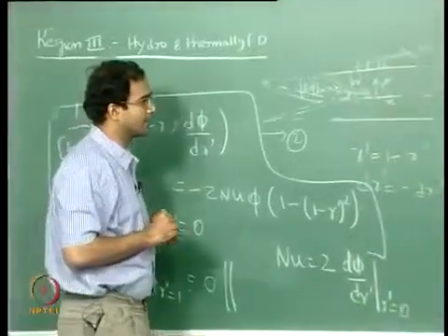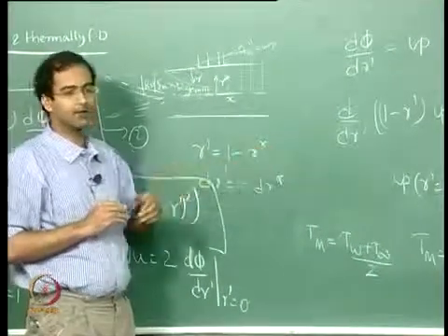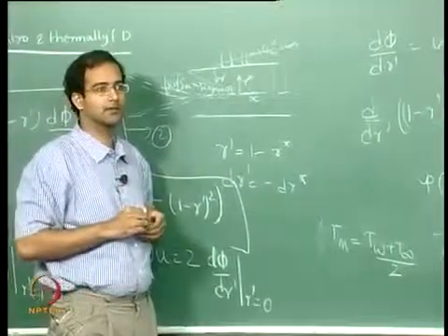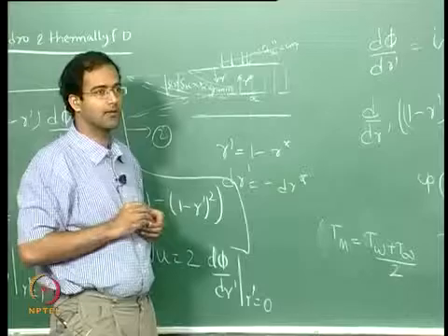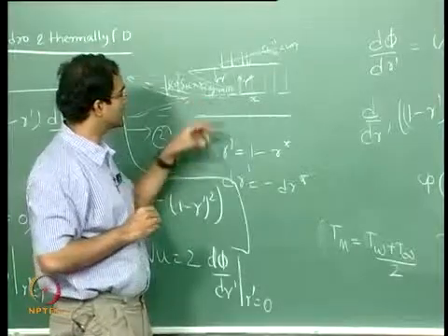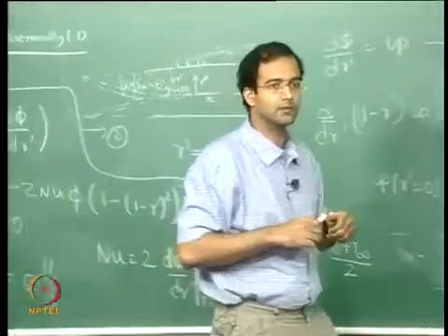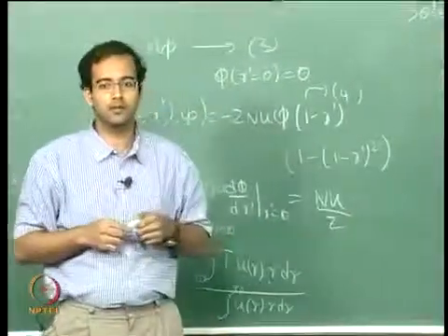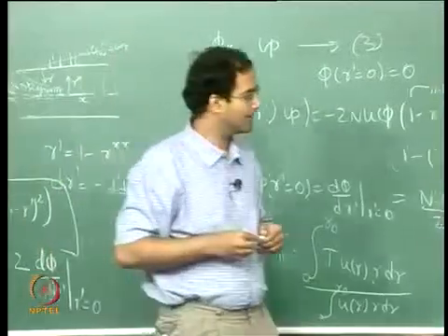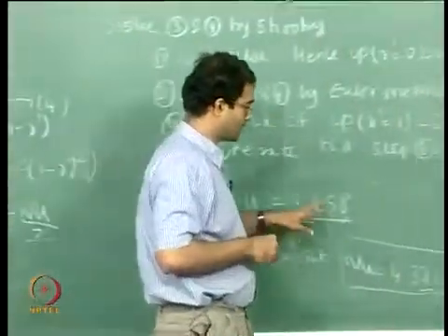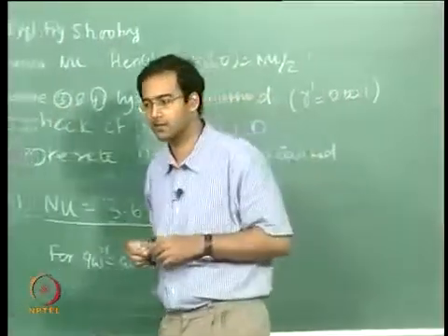What people say is that the variation in the properties is much more in the constant wall flux boundary condition than in the wall temperature case, and this will result in instabilities in the thermal boundary layer, which will possibly drive the heat transfer to be much higher than in the case of constant wall temperature. Okay. So this is one possible explanation, although in the textbooks it is not even mentioned, they just say generally that this is higher and they stop there,